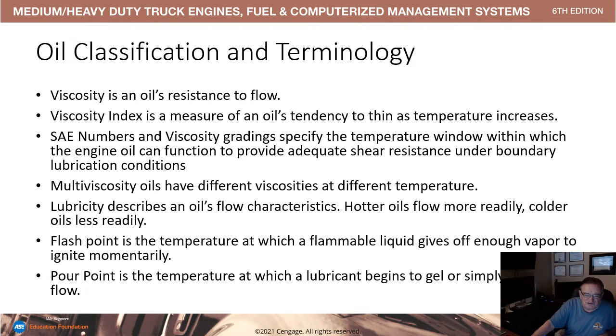Viscosity is oil's resistance to flow. The viscosity index measures how oil thins as temperatures increase. SAE, Society of Automotive Engineers, viscosity grades specify the temperature window within which the engine oil can function to provide adequate shear resistance. Viscosity is shear resistance.